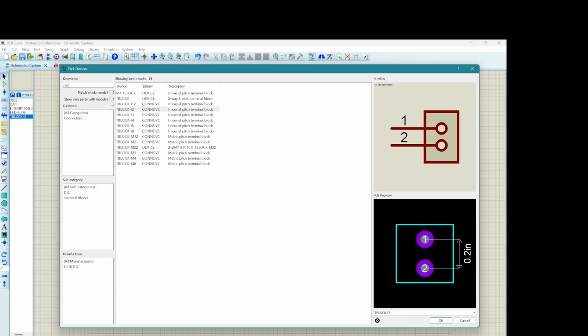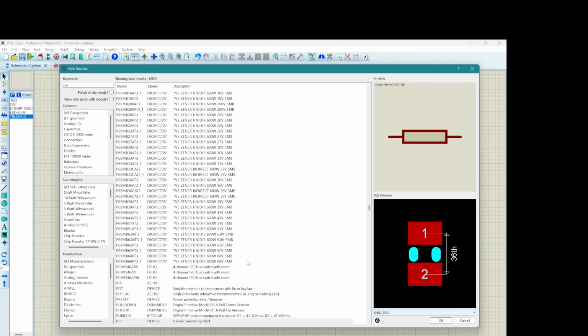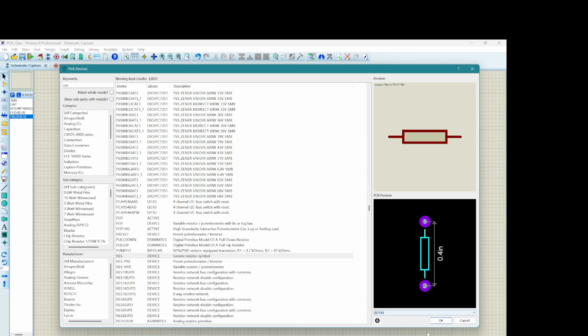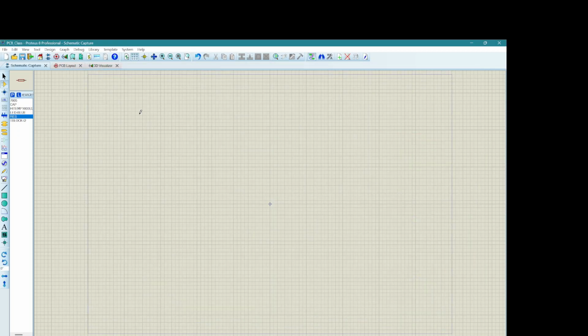So we've selected our LED and our high temperature capacitor. We've selected our filtering capacitor, and then we'll be selecting a couple of other components. Our 7805, which is the main voltage regulator itself. And then we have a T block or a terminal block that we'll be using as well. These are just some of the few components that we'll be needing.